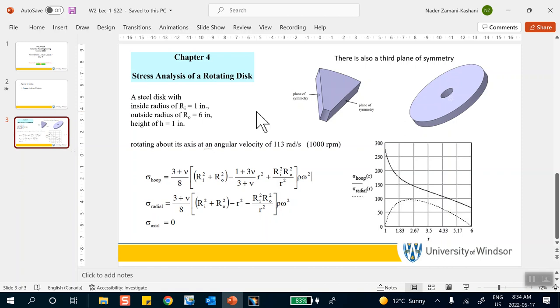But if, for example, this was pressurized, hypothetically, with pressure on the outside, or on the inside somehow you could have exerted pressure, then radial stress would not be 0. But in this case there is no pressure, so it's just 0 inside, 0 outside. Radial stress is biggest in the middle. That usually doesn't happen. Usually the biggest stresses are on the boundary, on the outside. But this is one of those cases, the biggest radial stress is actually inside of the part.